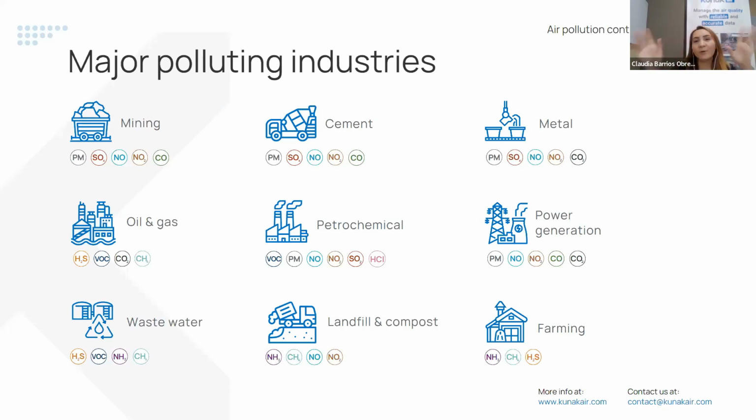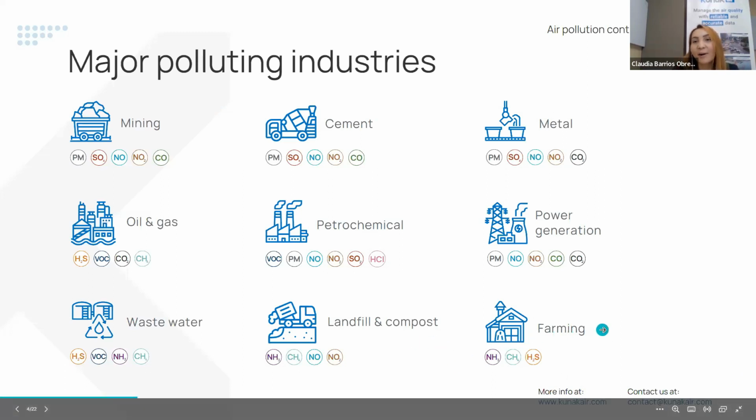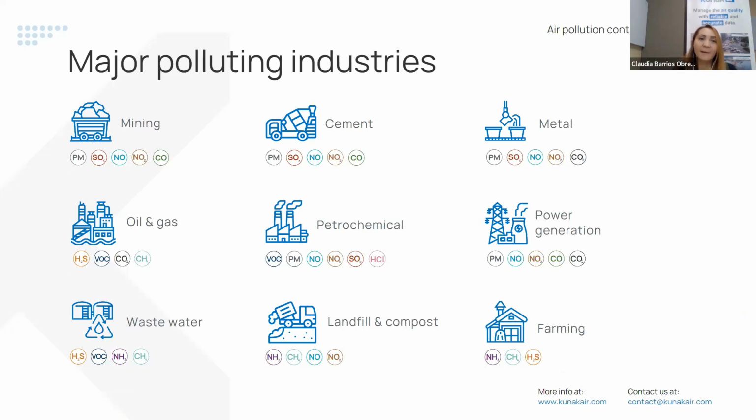Lastly, we have the wastewater group. The waste disposal industries can generate hazardous waste that must be properly disposed of, sometimes in facilities that can create significant air and other pollution, like landfills, compost, farming, or different waste treatments. And through the various treatment phases, different gaseous pollutants are produced. The most common are H2S, mercaptans, and ammonia that can produce intense odorous nuisance affecting nearby communities.